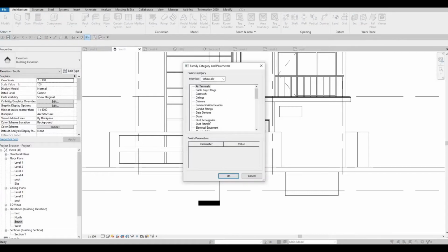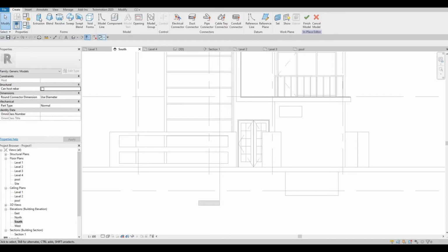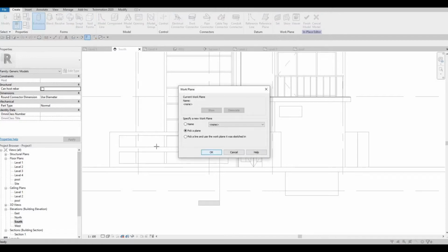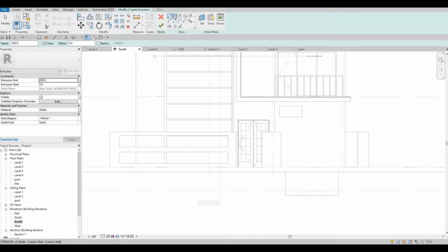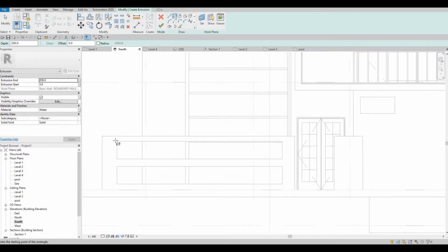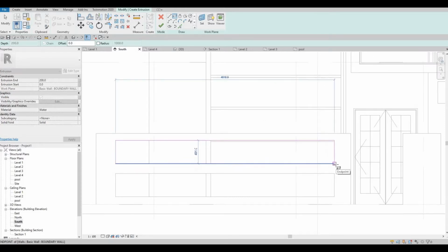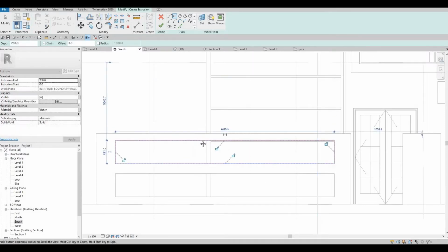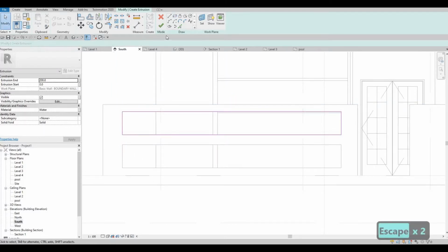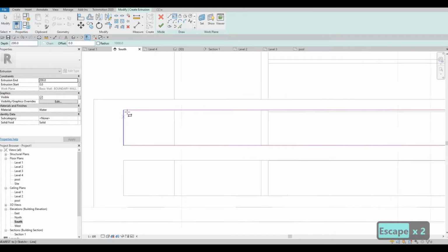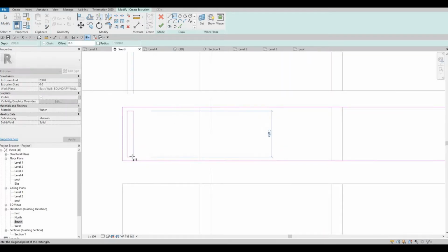So we'll make that from here. We're gonna go to generic model and then extrusion, pick a plane. We're gonna choose this wall as our plane, and here we're going to add in some design here. So this design will be very simple. It's just metal that is